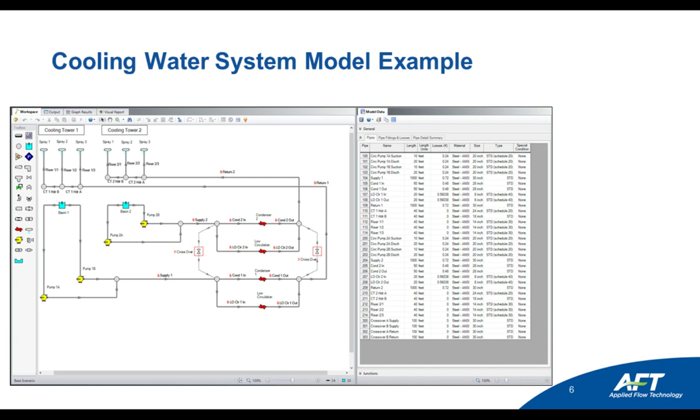On the right-hand side is an example of what the input information might look like, where all of the pipes are labeled for the various runs that they're in. You can see the various sizes and lengths of the piping. Some pipes have additional losses included. Wherever you see those red ampersands, that means for those particular pipes we are lumping in the minor losses with the piping themselves.